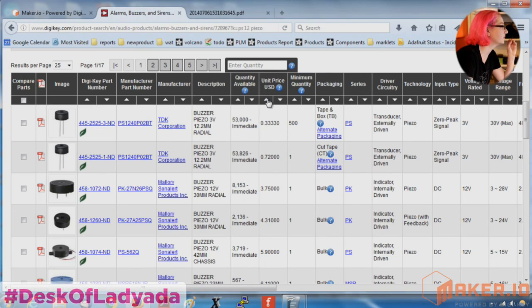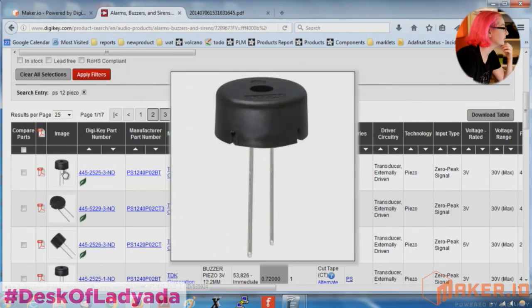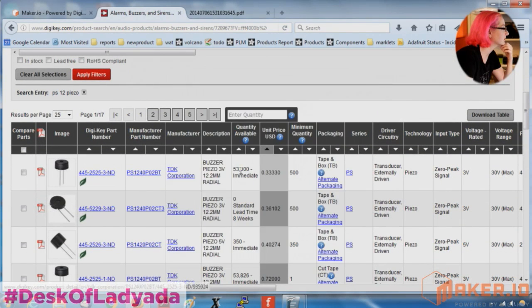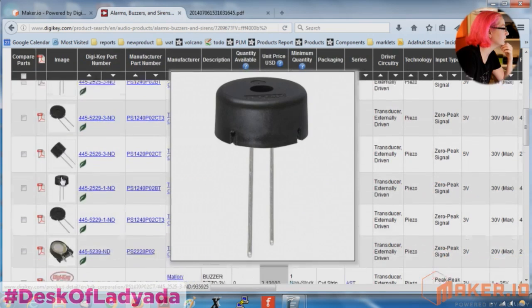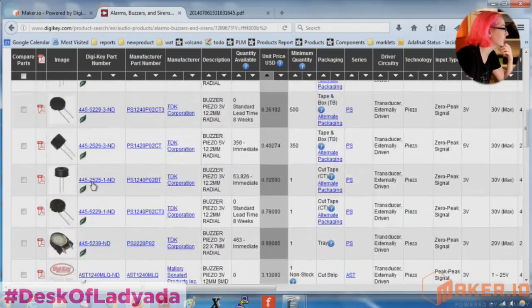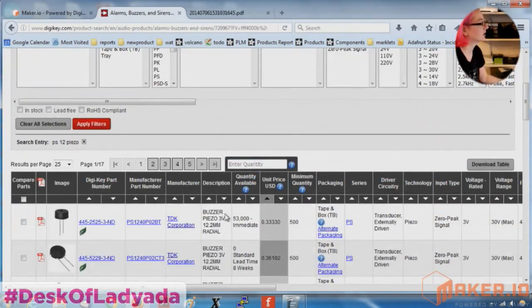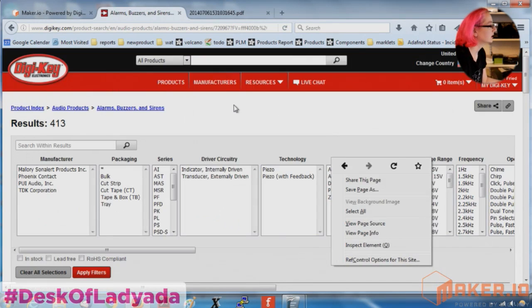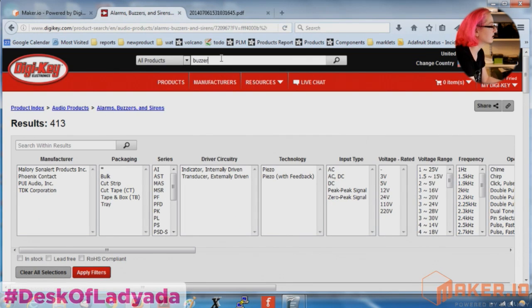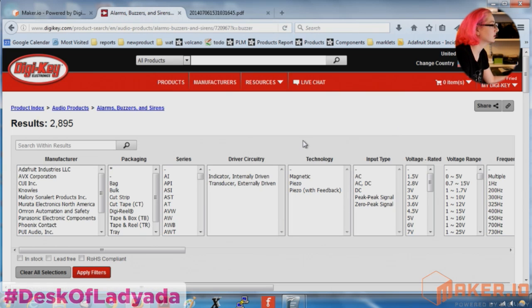So even if it's not that expensive, and they're like 30 cents, they are through hole, and so you can't process them the same way, which is, again, a trade-off. I wanted to keep everything surface mount. I was actually still thinking, okay, well, it's worth it to hand solder it if I couldn't get a buzzer for a good price. And I ended up finding a vendor that could get me a buzzer for a reasonable price. Well, let's see if there's something similar here.